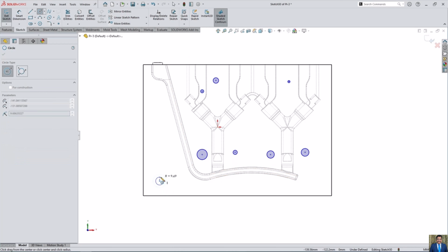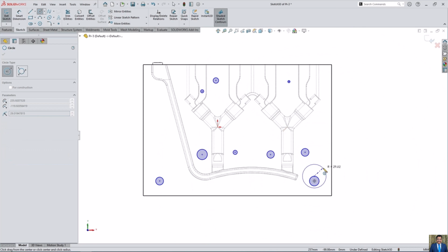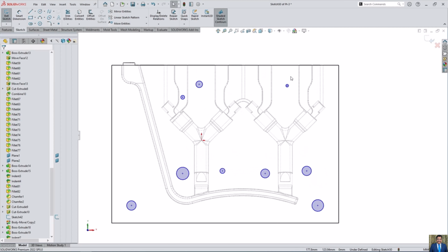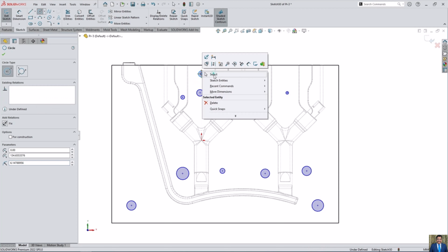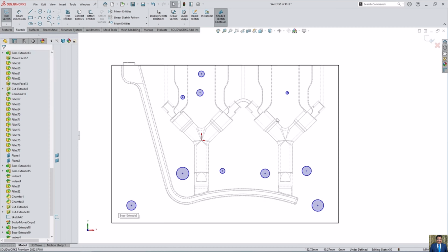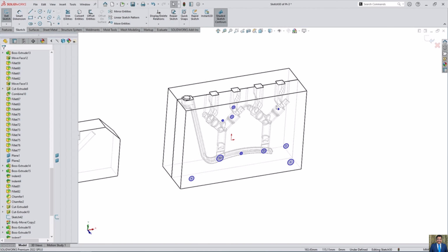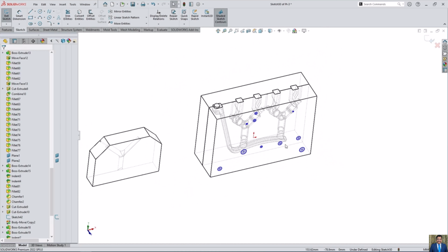And we also need a pin for mold orientation. We can have one here, and also, this depends on which place we want it. If we want, let's move a little and have one here. And it's no problem with 3, because 3 is enough for mold orientation. And we have completed all of our mold. But I leave it like that, and you can continue, and if you have some problem creating the pin,